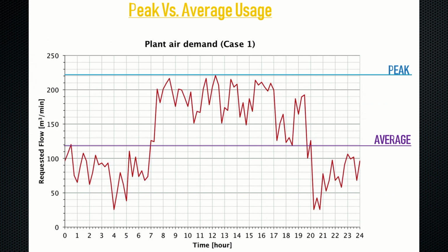Let's say that peak load is very short-lived. Then you can use storage tanks. The other way to do it is to run both compressors in order to meet your peak demand. If a single compressor can handle peak load, it's probably running unloaded most of the time, and that makes it a good candidate for one of those variable speed drives. Sometimes you have to tackle end uses, but hey, that is discussed in our next episode.